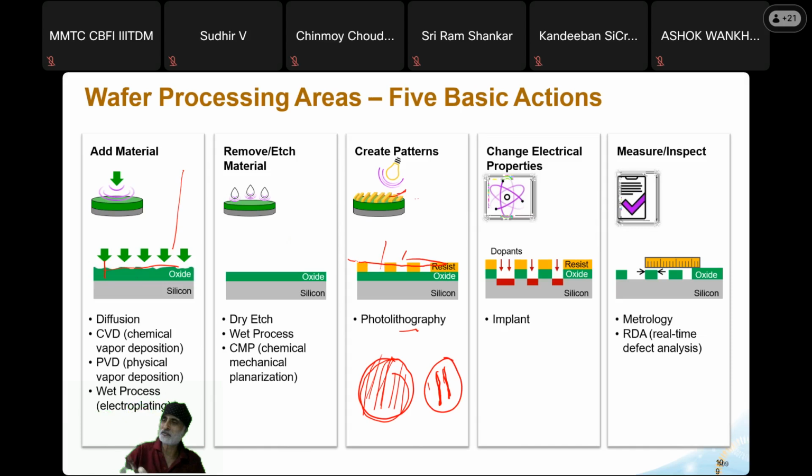I cannot open this box. This is basically made of quartz, and one mask costs around $7,500 to maybe around 15K or 20K US dollars. So the mask sets are expensive, and they contain this information. And masks are made from the GDS, which is submitted by the designer, depending on the design of the circuit. Another thing, the process is implants.